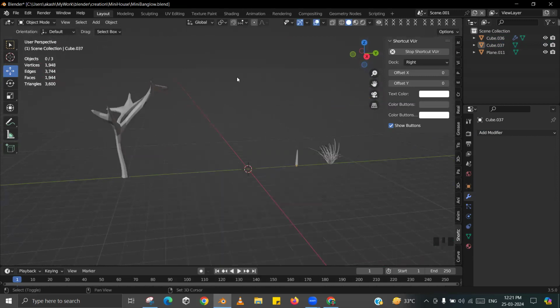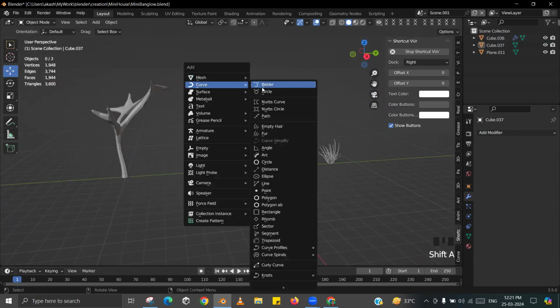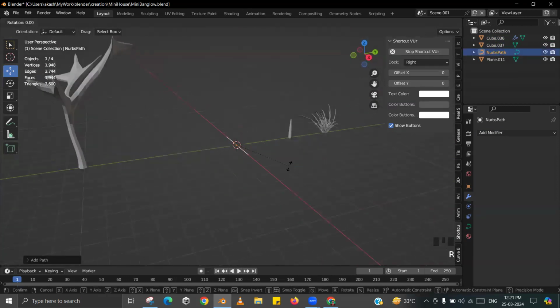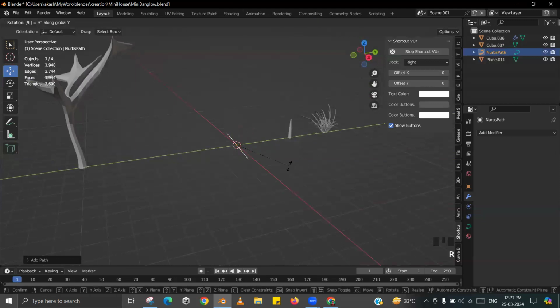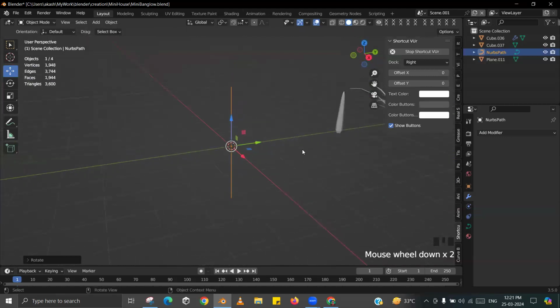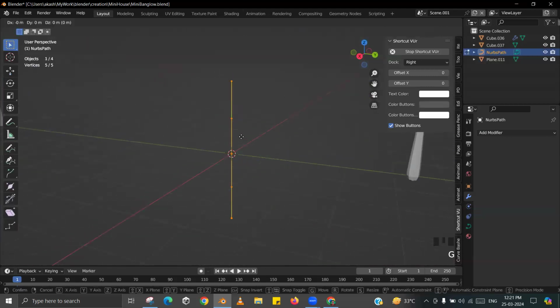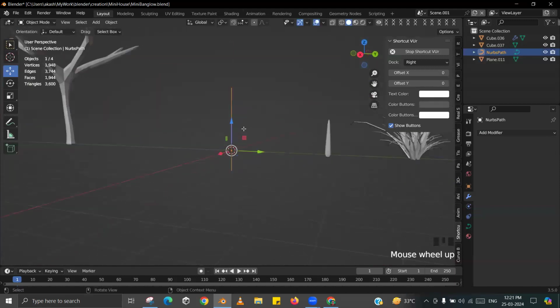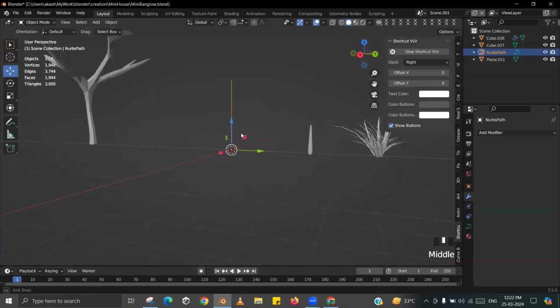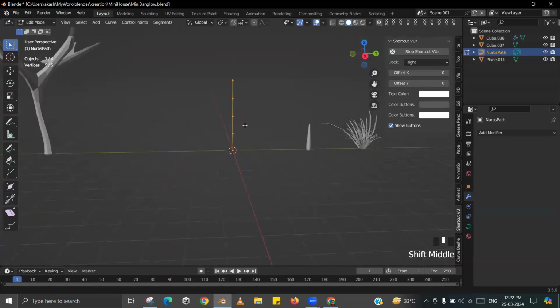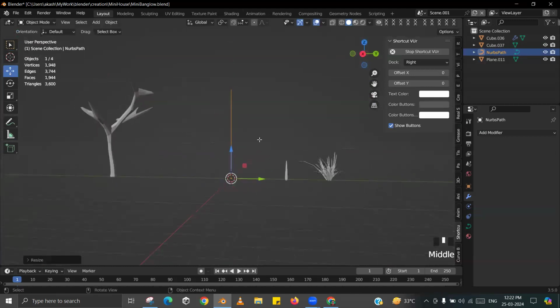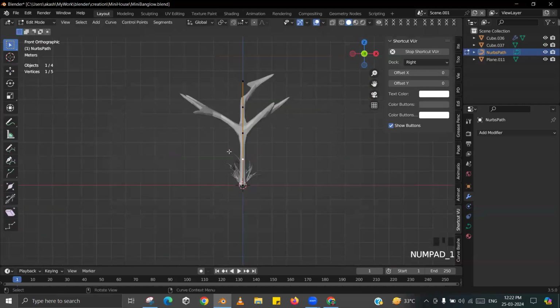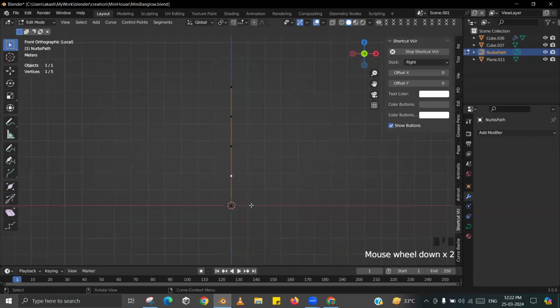And to do that, what I need is let's take this tiny curve, numpad, rotate along x 90, rotate along y 90. Okay, G along Z, again G along Z. What to do this time is S along Z, somewhat like this.